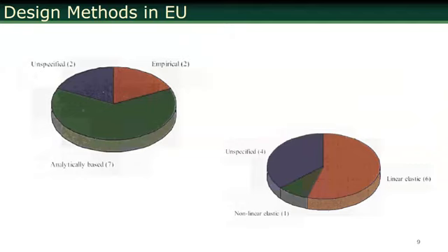And among these analytical methods, most of them also use linear elastic solution. Some of them use nonlinear elastic solutions. So it looks like some of the countries in Europe are actually using nonlinear elastic solutions for structural analysis. The other ones did not report. So this was interesting when I saw this, because I would always assume that empirical would be the most, but they are using analytical approaches most of the time.